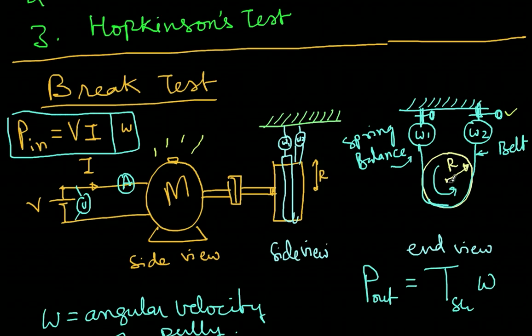So you actually pour some water into the drum, and when the belt and the drum move across each other, there is friction, and that friction will heat the water, or in other words, the water will cool the drum. The water actually converts into steam, boils, and then goes off. So that is one way to control the temperature of this particular drum system.